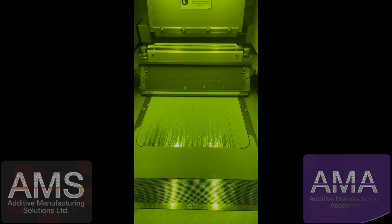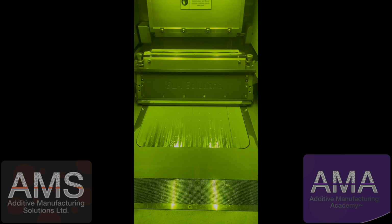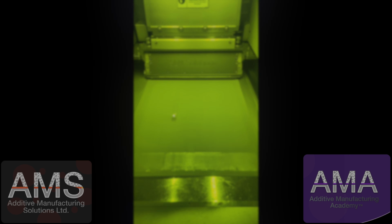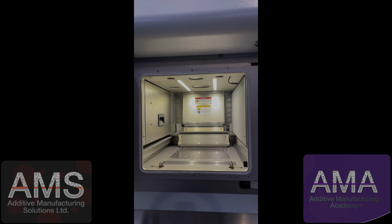The doser collects powder and then will coat forward and backwards to put down a single layer of powder. The laser will then selectively melt the areas that we want to turn into solid before the recoater returns over for another layer, another layer, another layer, continually dropping by the same layer thickness. We then will potentially process thousands of layers before we end up with our three-dimensional part.